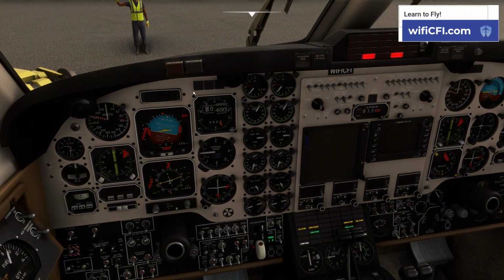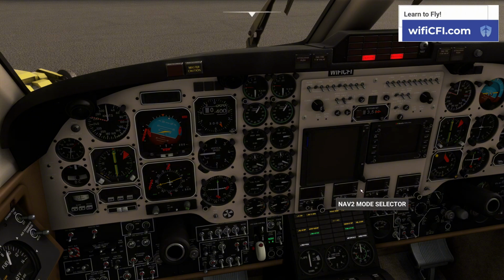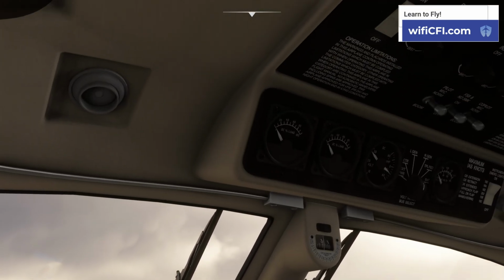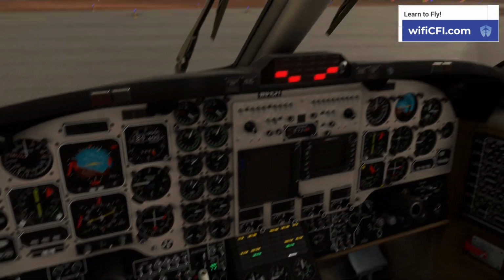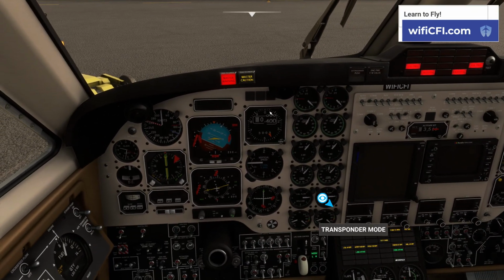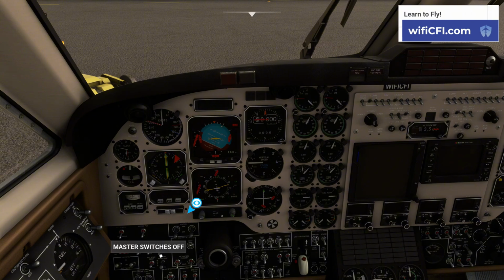ITT, come up here. Double check that it's been stabilized for a minute. We can go ahead and get these guys cut off. Air condition levers, propeller levers. We're going to bring those back. DC voltage, we could then come up here. Check our current limiters. Overhead light switches off. Oxygen supply control handle, we'd go ahead and push that back in. Back behind us. Get our beacon off now. The engine's off. And then I think we can just, yep, we check the tach time. And then boom, gang bar that down.